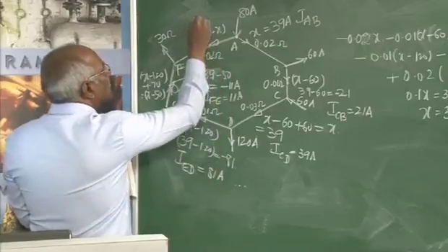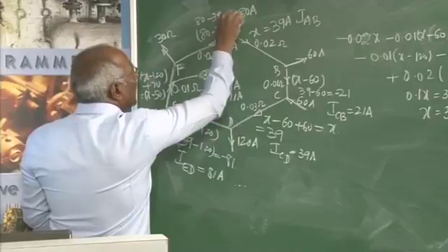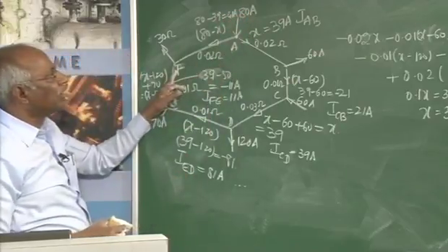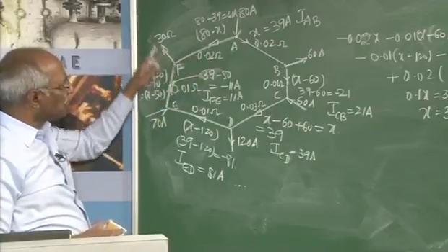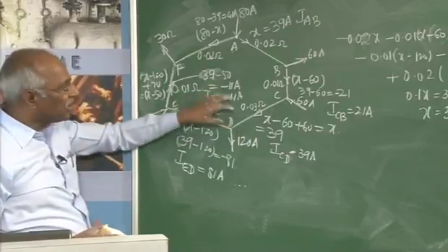And here it is 80 minus 39 comes to 41, indicating that the current is flowing from A to F only. As 41 amperes comes here, 30 amperes goes this way, and 11 amperes comes this way, indicating whatever has been done is right.